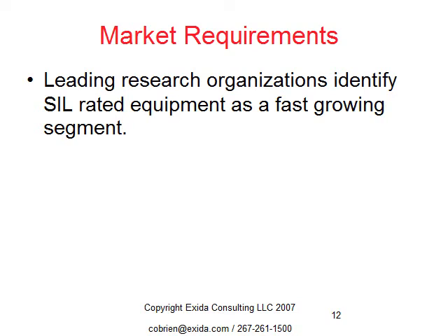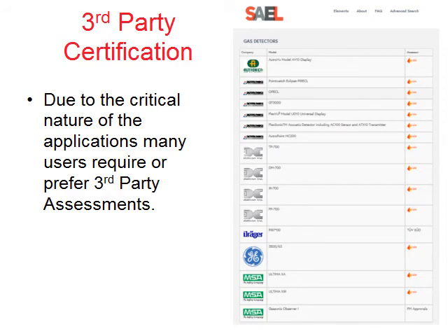I think about 15% of all gas detection loops right now are SIL rated loops, meaning they're going into SIFs. So a fair amount of the gas applications are already SIL related. End user customers are looking for third-party certification of equipment, driven primarily by the critical nature of the application. And even if it's not a SIF, by its nature, looking for these toxic gases or explosive atmospheres, obviously there's a lot of risk inherent in the processes that contain them.